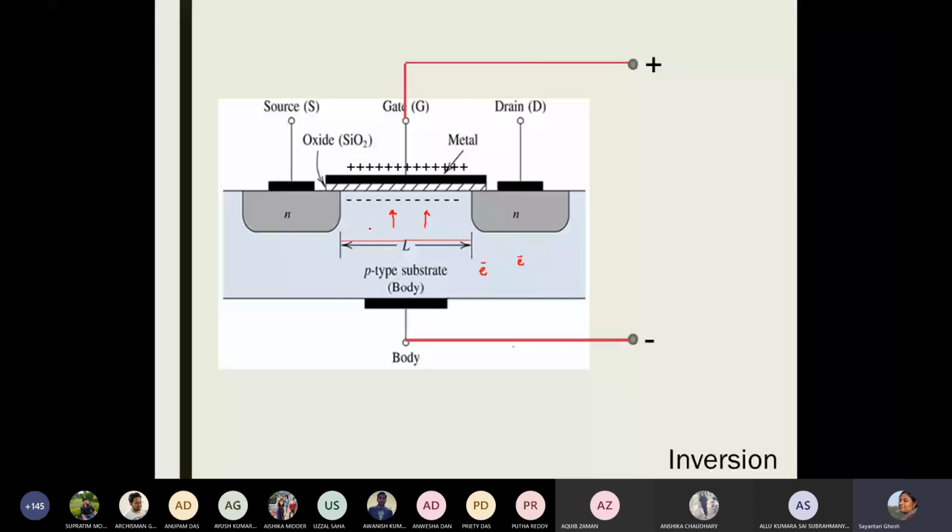So effectively, what you will have is a capacitor-like effect where lots of electrons will be crowding on the top surface near the semiconductor material. They cannot leave the p-type substrate because the insulator is sitting here. So just near the top surface, we'll have a huge crowding of electrons. Let us think about what is happening. We had a p-type substrate. This entire thing drawn in light blue should be behaving like a p-type material.